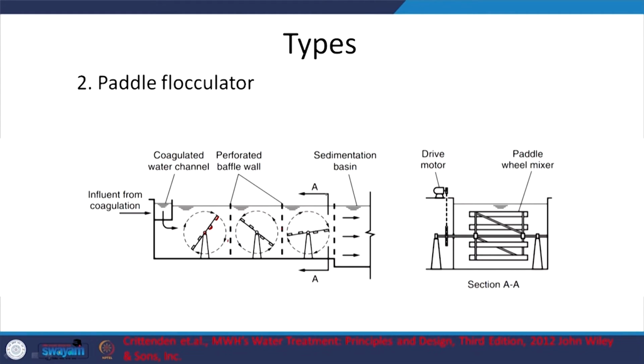So if I cut it at this section and look at it this way, this is what a paddle looks like. I am looking at it from this way. So it's mounted, and you have the drive and you have the paddles. You need to be able to design these, as in what is the width, what is the distance between two paddles, how many paddles and such, because that will determine the power from this motor being transferred via the paddles into the water. So that's why you need to be able to design these aspects.